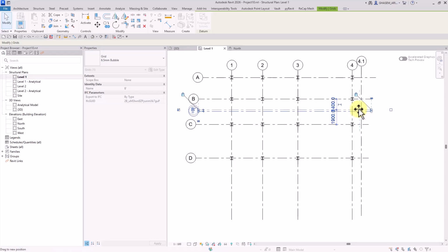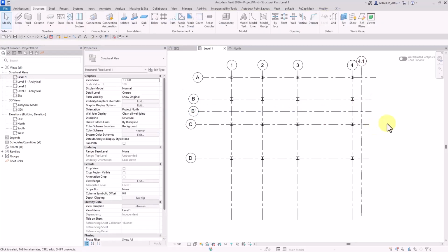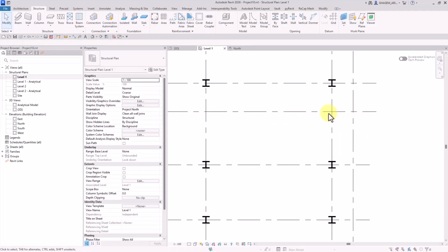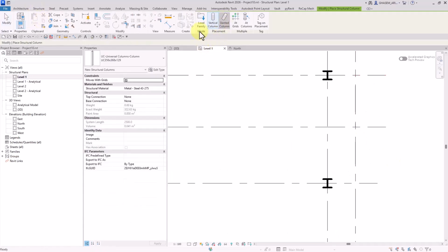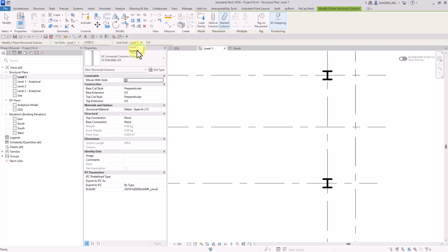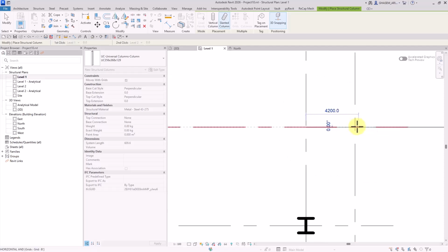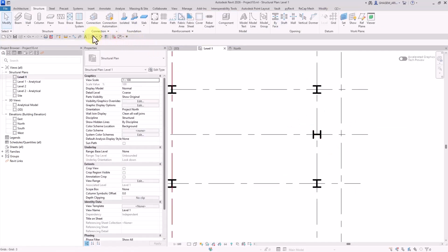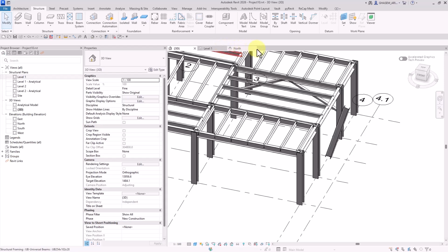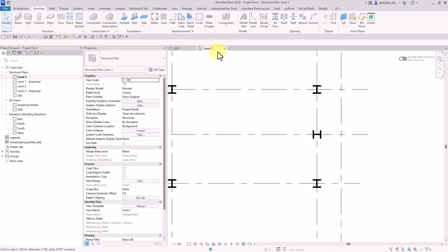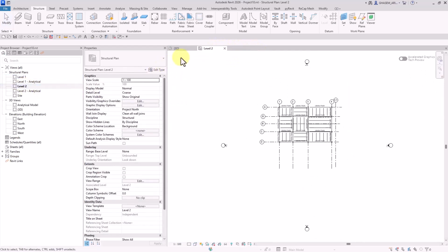Oh, this is good actually. Control Z. Yeah, that'll do. As I said, let's say we want to work with a slanted column from the first level to the second. I'm going to try setting this column right here. Yeah. Let me check this. Okay, now we got this diagonal column. Now again, let me set both views next to each other.